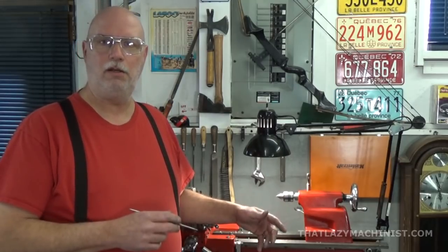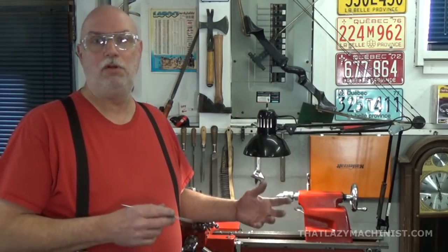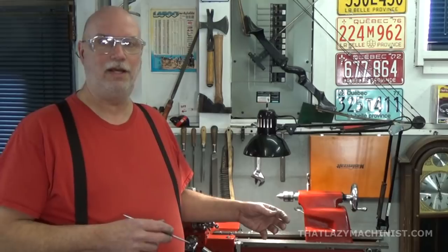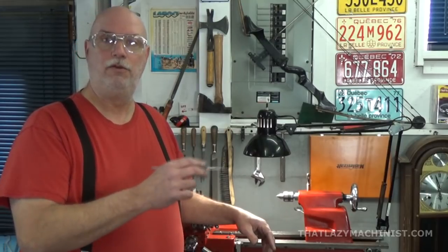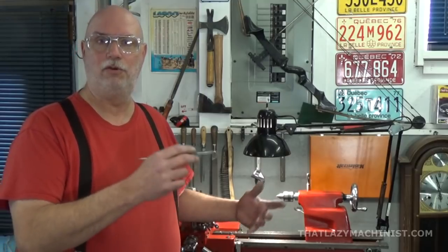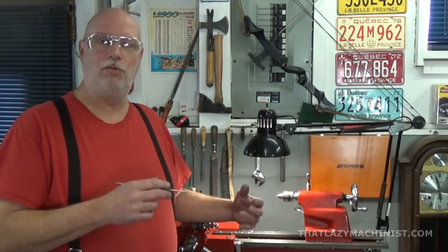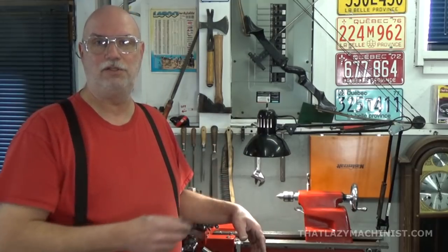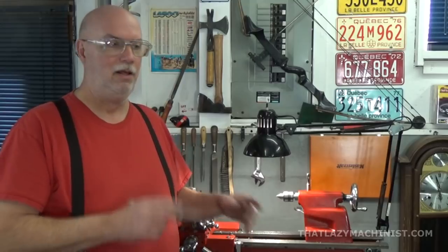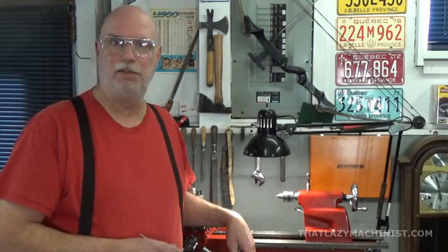Now we're going to start a little counterintuitively, because most people would start by turning the 200/1000ths of an inch diameter full length and then work down to the 100/1000, then work down, and so on and so forth. But that is a problem, because that means that when it comes time to turn that final 25/1000ths of an inch diameter on the end, my whole part will be at its maximum of flexibility.